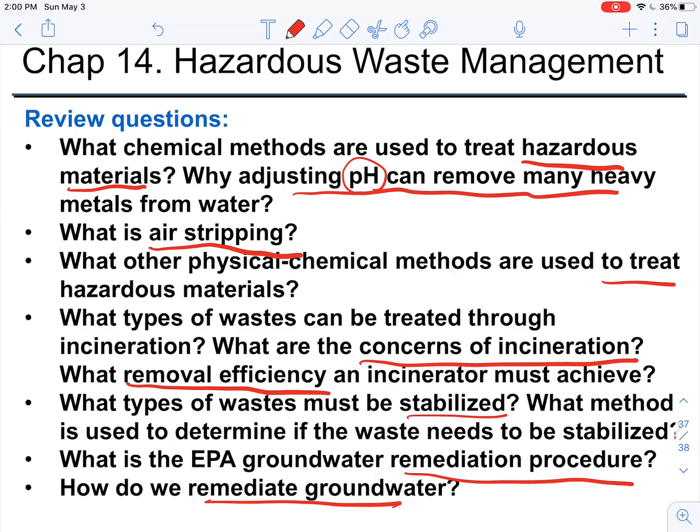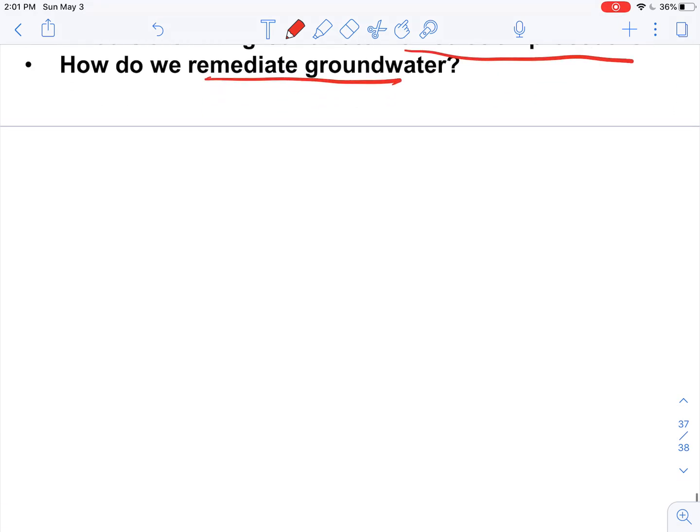And then we introduced how the dissolved oxygen is being distributed in the river system or in all different types of water systems. So more specifically, we talk about the DO-sag curve. Once we dump in some pollutants in the river, we can see the dissolved oxygen will decrease and then come back because the oxygen is being dissolved in the water.